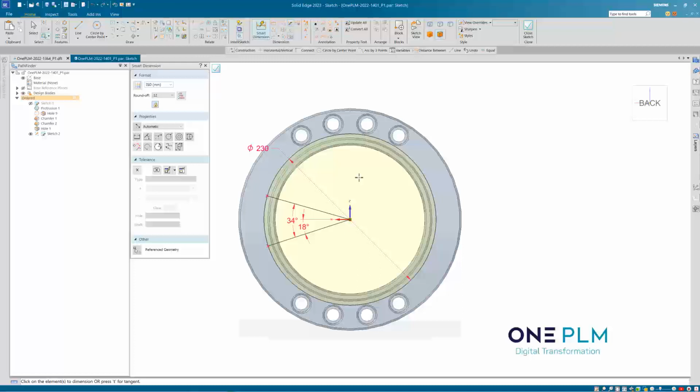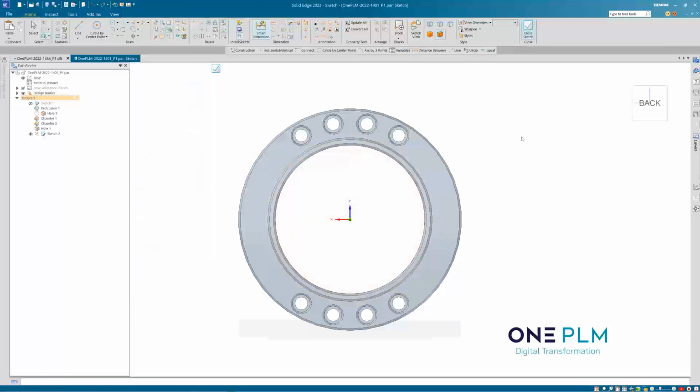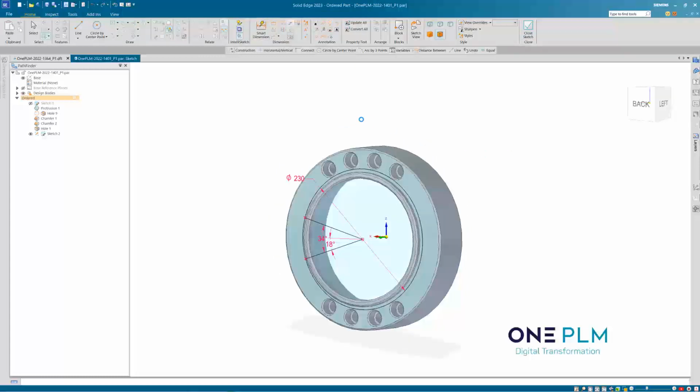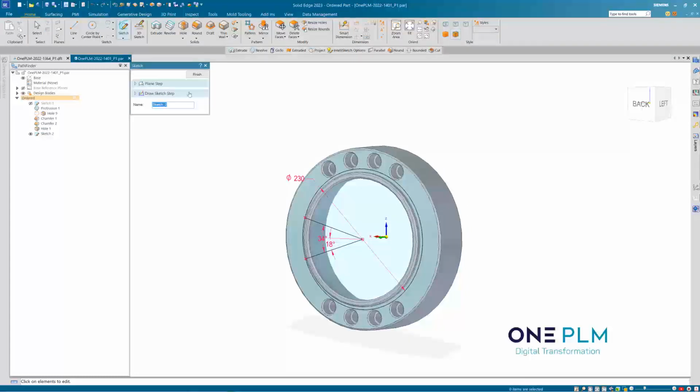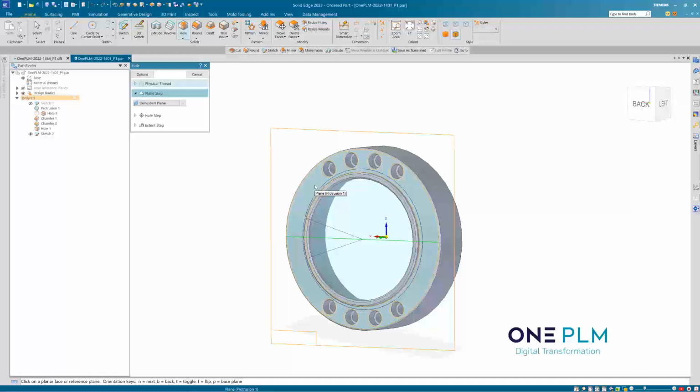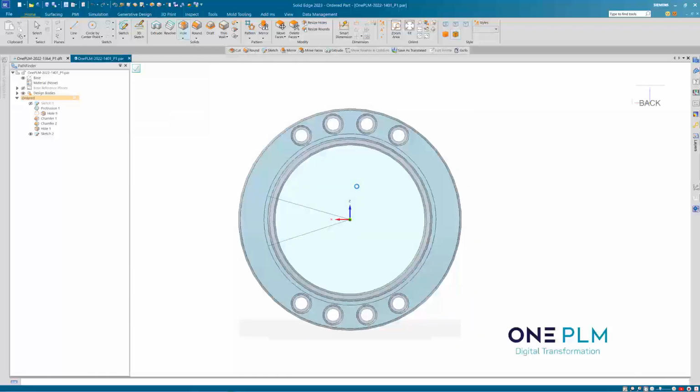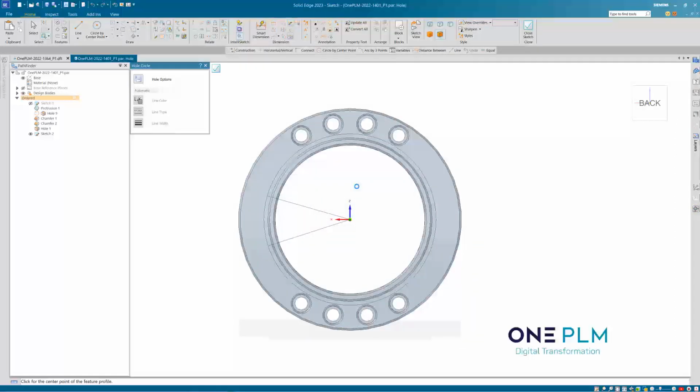So this is our sketch. We're going to put one hole there and pattern partial that way, one hole there, pattern that partial that way, with different angular spacings. So if we close that sketch and finish, and then go and find our hole command. So with our hole command, we're going to go onto that same plane we chose before. We can actually snap our hole directly to these. So I'm going to do the first one first. So we're going to snap on there,